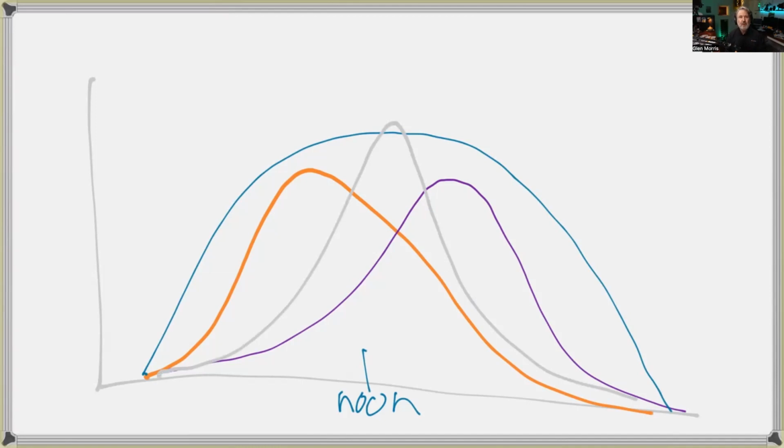East and west will give you a longer production cycle. And for an off-grid system, it tends to be the morning is when you want the energy because you've used it up overnight and you're just aching for the sun to come onto your panels. An east-facing array will get that sun first and will help you recover quicker from a dip overnight.